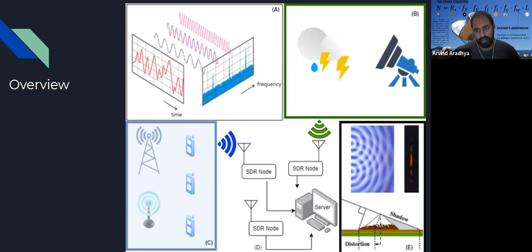And that's insidious enough. But there's also the fact that when you have reflections, you can have constructive and destructive interference. So you drop 2 pebbles and they produce their own ripple patterns, and then that causes a spike in the water level at one point and a trough at another. If you have a trough at some point, then that essentially means that you're not getting any signal strength. So this is called multipath, and it happens all over the place. Especially in an urban environment where you have high rises, every flat face of a building acts like a mirror to an extent, and it bounces signals off, and then you get something complicated.